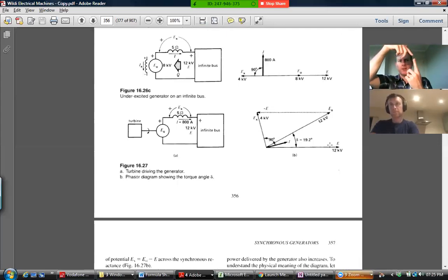So it would normally naturally sit that all the norths and souths lined up and they just move together. But now the rotor is going to be tugging ahead, so to speak, of the rotating magnetic field. So when it moves ahead like that, there's a certain number of electrical degrees delta, which will correspond to the number of mechanical degrees on the actual physical machine, where there's a relationship that takes into account the number of poles or pole pairs. At the end of the day, the electrical one is what we want, so one sees it here